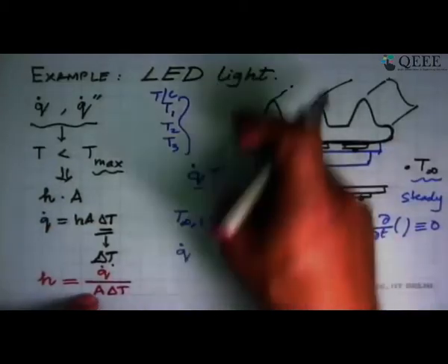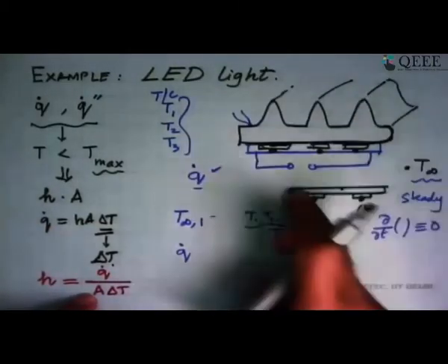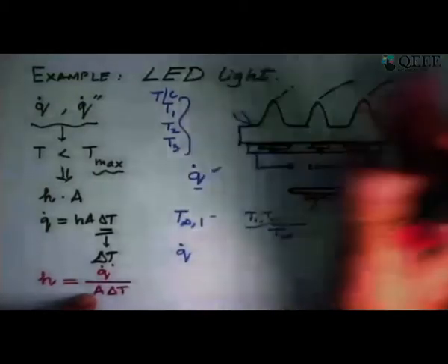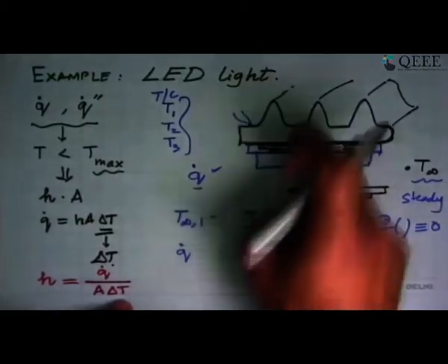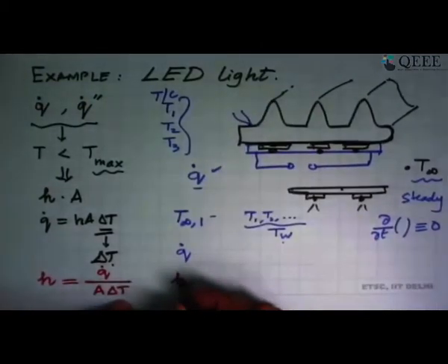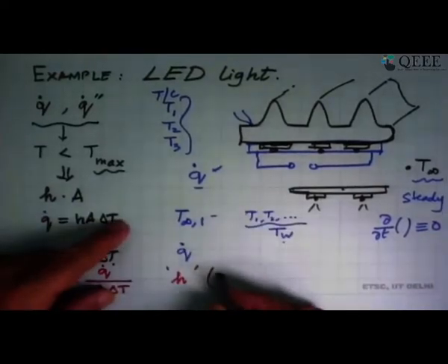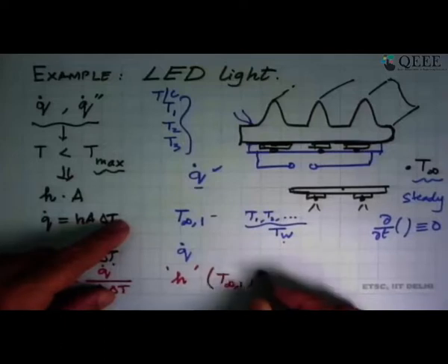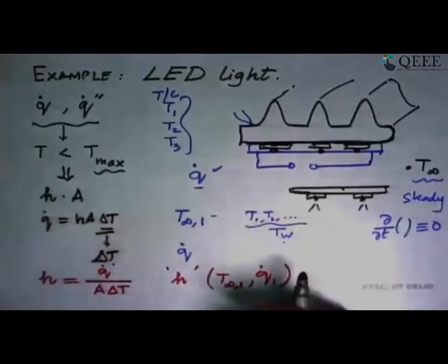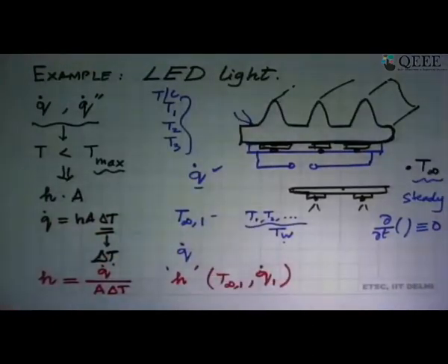A, we were able to measure from the geometry of what we put, whether it was a flat plate or this thing or with more of these things. And delta T is what we measured. And from here, we get value of H for that particular combination of T infinity, which was T infinity 1, and Q dot, say 1. And we have already fixed the area. That is one experiment. One data point has come.